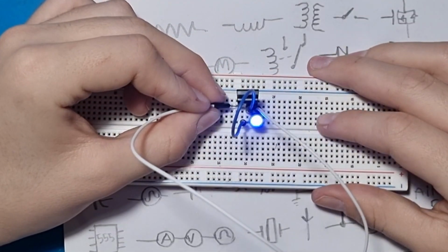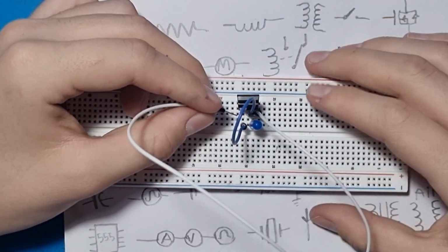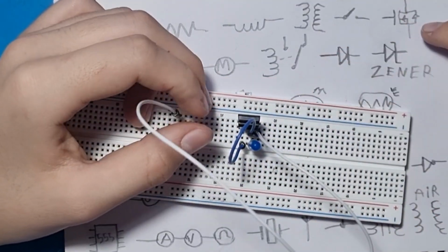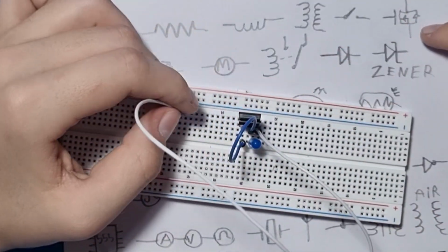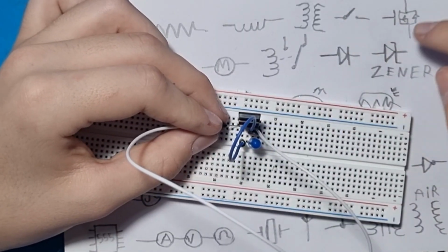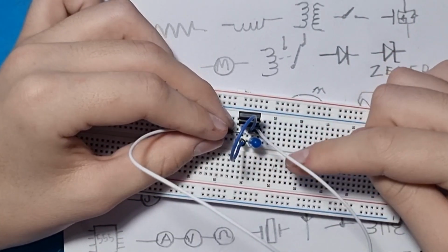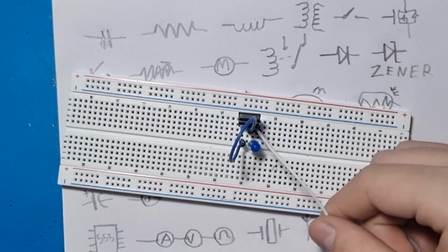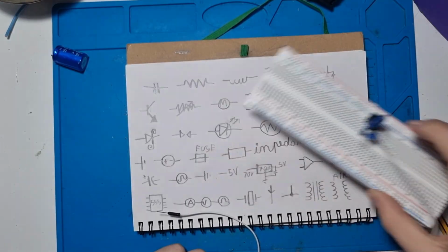So now I'm tapping the gate, and when you charge the gate, it allows current to flow between the drain and the source. Now I've tied the drain to the gate because I need the same voltage. If I need a higher voltage, I would have fed it off a different power supply. And the source is ground, and I can use it as a small switch. This is a breadboard, these are the wires, and this is an LED.